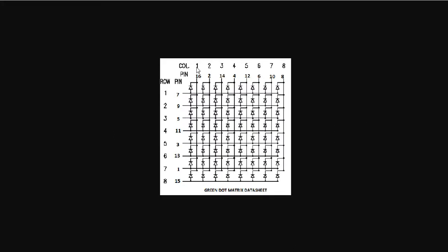When you come towards the ULN2803 side, there are 1 2 3 4 5 6 7 8 columns. So there will be 8 columns over here, 8 columns over here, and these columns will be combined with this upper one, and this will be combined with the other one. So you are going to have one ULN2803 IC over here, and this ULN2803 IC will be connected with another IC, the 74HC595 over here, similarly 595.